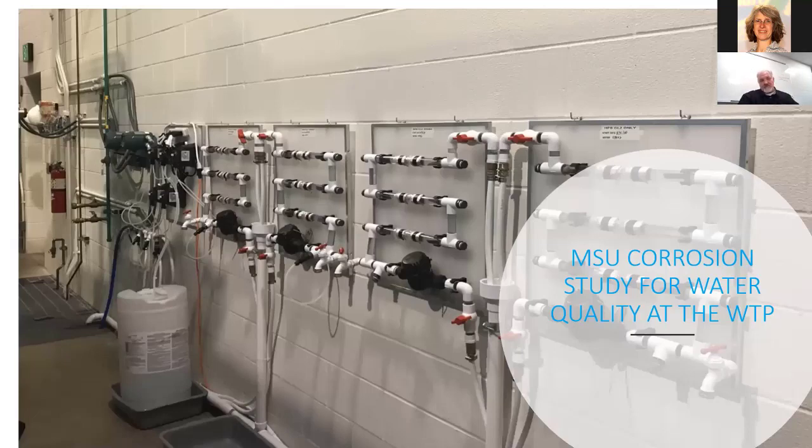We are applying a phosphate mixture of 70% orthophosphate, 30% polyphosphate, and applying at the 3 different rates of 1 part per million, 1.5 parts per million, and I believe it's 2.5 parts per million.